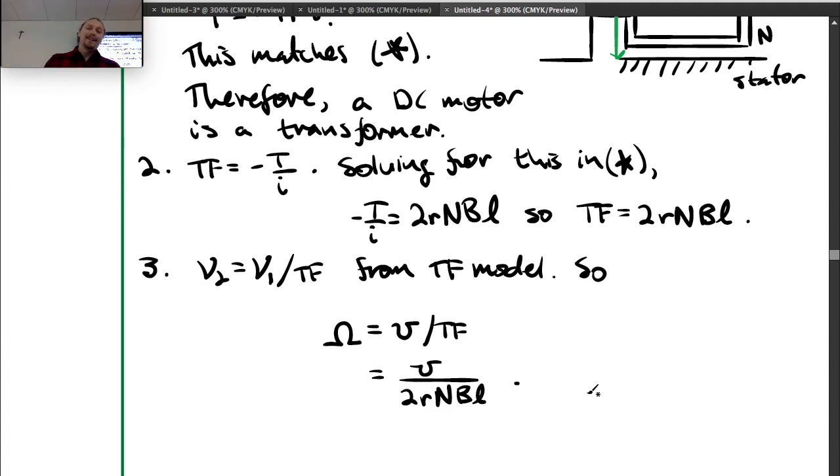It's good because the torque goes up, right? But as the torque goes up and the current goes up, if you remain stuck and you don't get going, the current draw gets significant. And again, it gets hot because there is some resistance in the motor. So the coils have some resistance. And if you start flowing more and more current through them, you get more and more resistive heating, right?